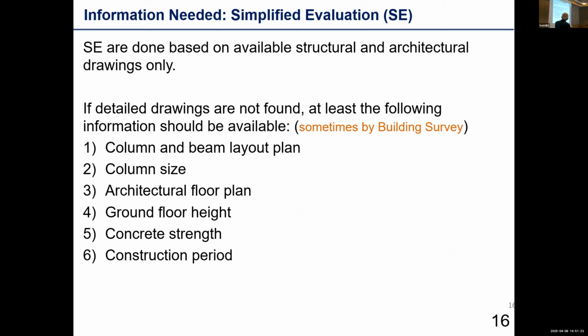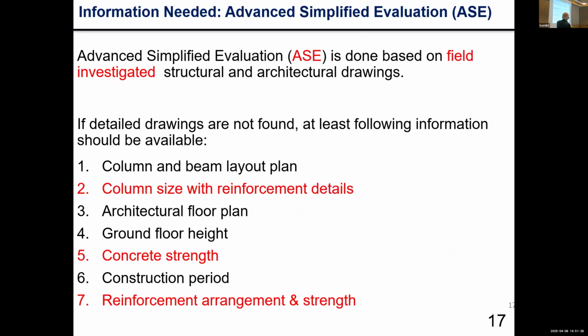For simplified evaluation, those rudimentary pieces of information will be required. And the concrete strength is assumed based on our research. In the case of advanced simplified evaluation, we have to carry out some building survey, including a Schmidt hammer test to know the concrete strength, and also the column size with reinforcement detail.